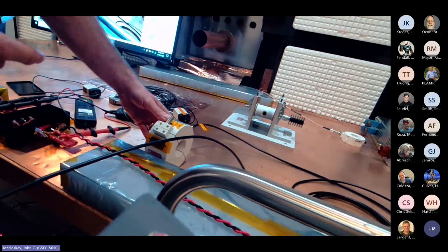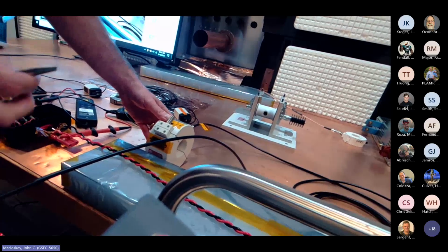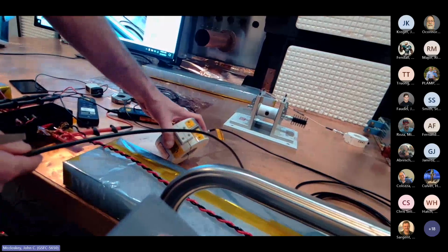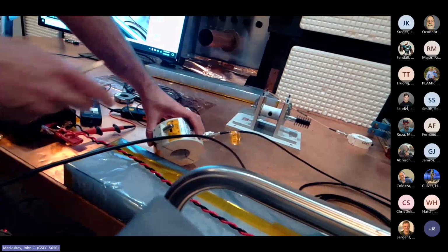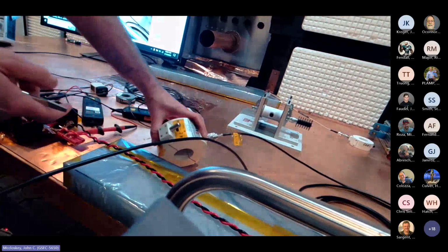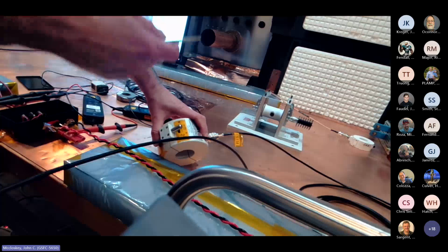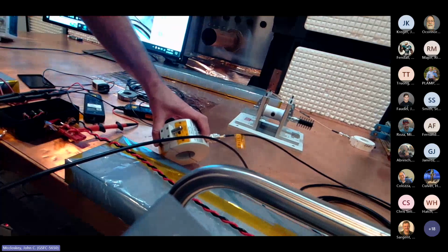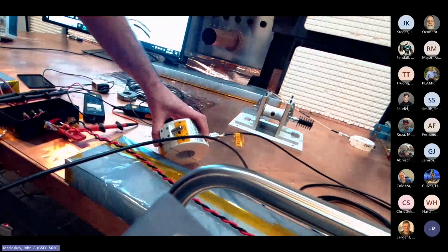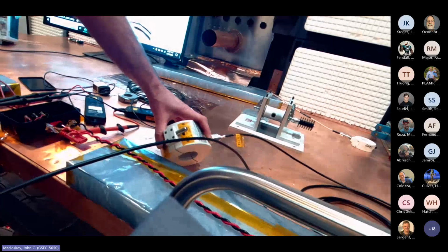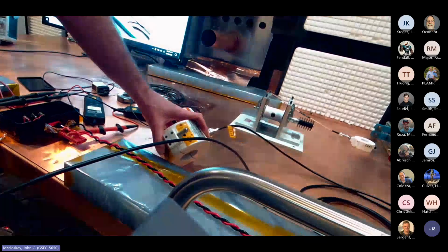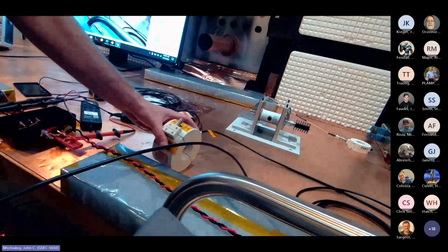But at 200 megahertz, you're going to have some. So it's just good practice to keep everything exactly the same. In fact, it's preferable to not even make any disconnections if you can, right? Because when you disconnect an RF cable and reconnect it, you might get just a slight change in behavior. Depends on, yeah, got an RF guy right here, and so yeah.